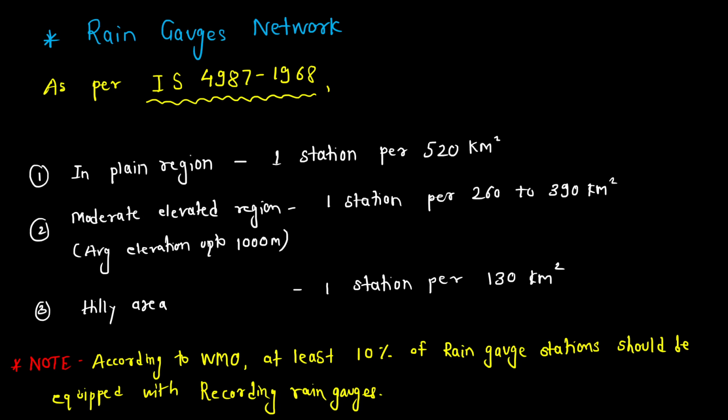So there is one more point, that is about the rain gauge station and the nearest building which is present near the station. So let's say this is a ground surface. Okay, so in this ground surface, there is a rain gauge station which is present here. Now, if there is any tall object, like any building, then there will be some hindrance to the rainwater which is coming here.